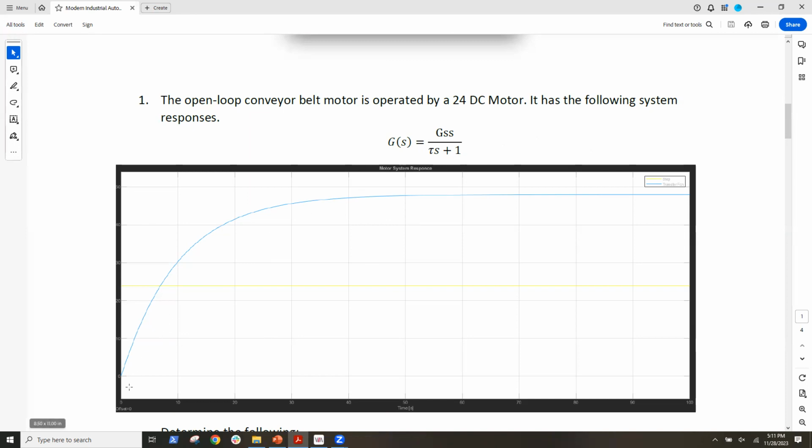You'll go up here, it's going to settle at a certain value, you're going to find 63.2% of that value, and then figure out the time response associated with that, and that's going to become tau. So this motor has a max speed. There's no way it could go faster than 57, or wherever it saturates. And so that's my top speed of the motor system.